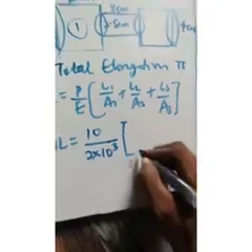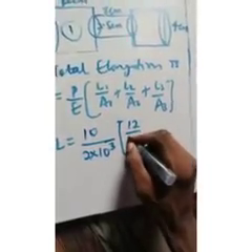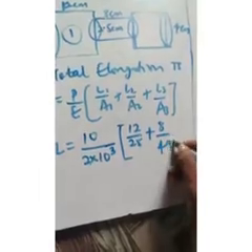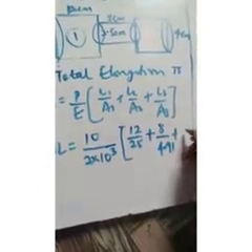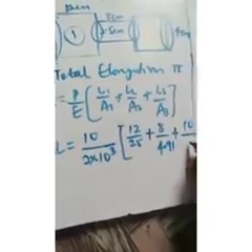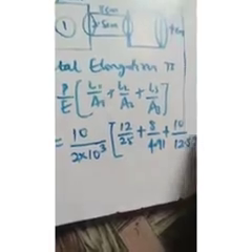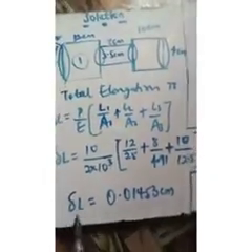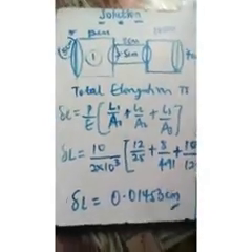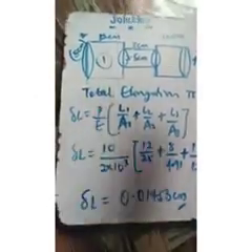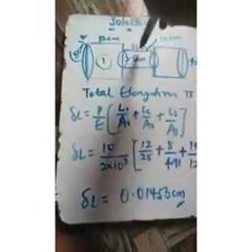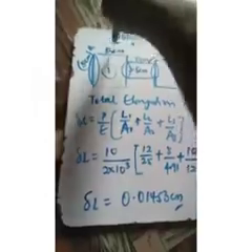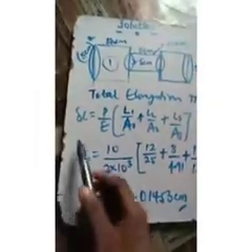So we have our L1. Our L1 is 12. Our A1 is 25. Our L2 is 8. Our A2 is 4.91. Our L3 is 10. Our A3 is 12.57. So like I said earlier, you're going to have the answer as 0.01453. So from here you can find out that the biggest stress will always occur at the minimum length, and you have the lowest stress at your longest length, and you can have your change in length like this.